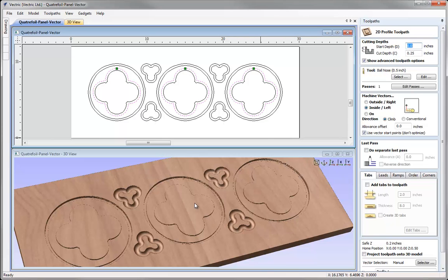Now you might think we want to start an 1/8 inch down into the material, as we have pocketed out this area here, but we've got to be careful of the fact that this shape here is still 1/8 of an inch, or literally the same height as the top of the block, and we don't want to be plunging down an 1/8 of an inch into that with our tool. So we're going to start cutting from the top of the block, and cut down an 1/8 of an inch extra than we need to. So I'm going to specify 1/4 inch plus 0.125 and then press equals, and that gives us the value that we're going to cut down.